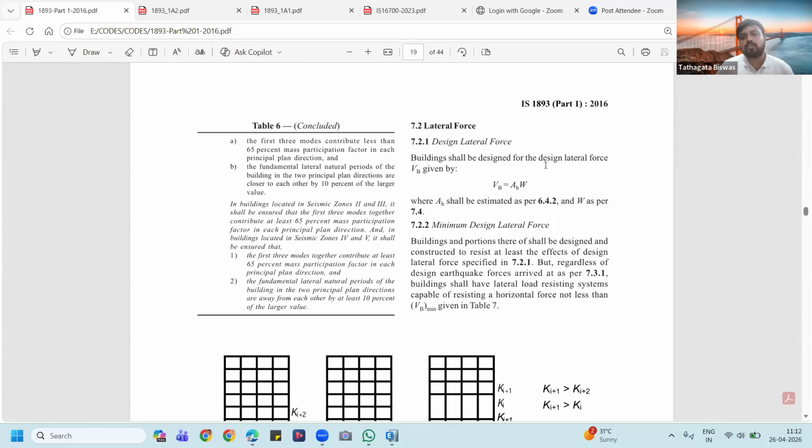Now, if you do not consider the static analysis, what will happen? This infill wall panel stiffness, which will actually be there at site whenever the building comes up, definitely there will be certain kind of wall material, right? It could be brick wall or block wall or any sort of wall. Apart from the beam, column and slab, which are the frame of the structure, there will actually be the infill wall panels coming up on top of that, and that is not a small amount of area. A complete structure would be covered by the walls.